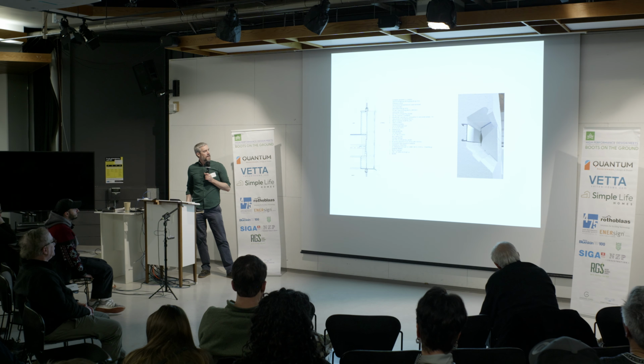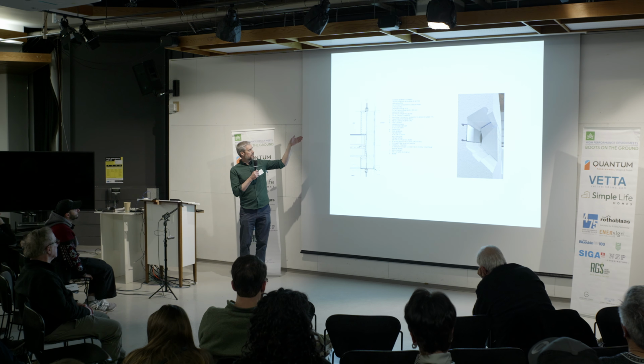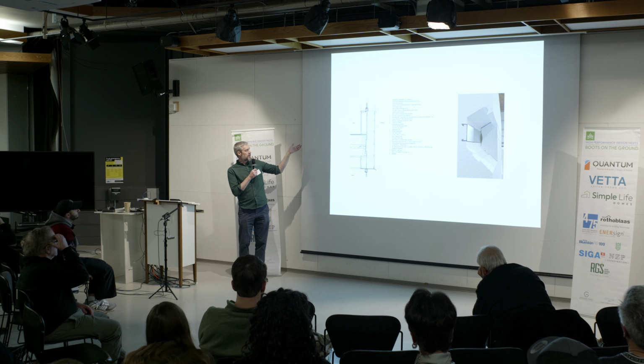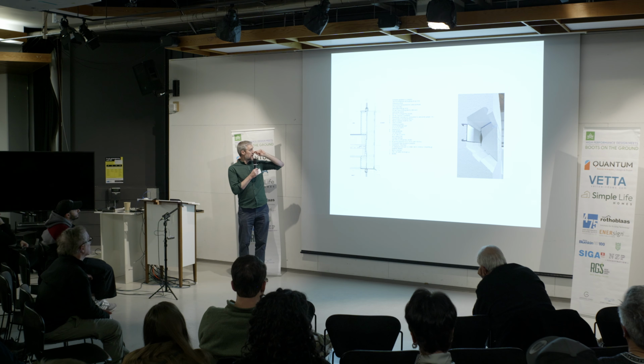Okay, so I'll talk a little bit about some of the details. This is the external wall. It's a wood frame building, dimensional lumber, so we were able to take advantage of vapor barrier on the inside, air barrier on the outside, with majority outboard insulation. We tested the dew point of the wall.